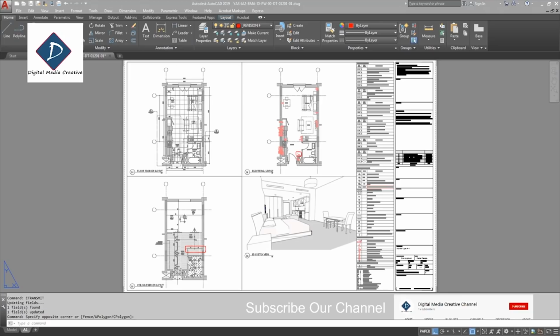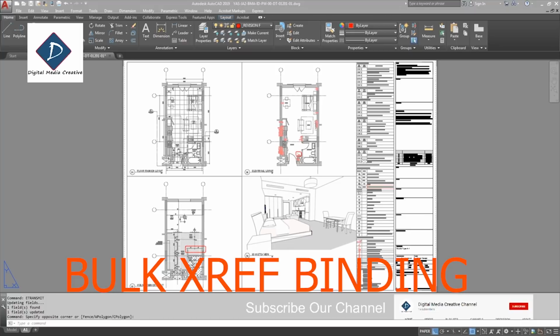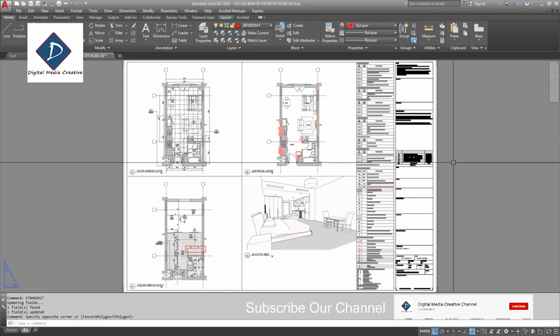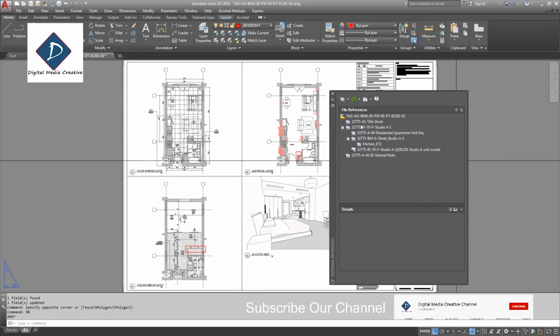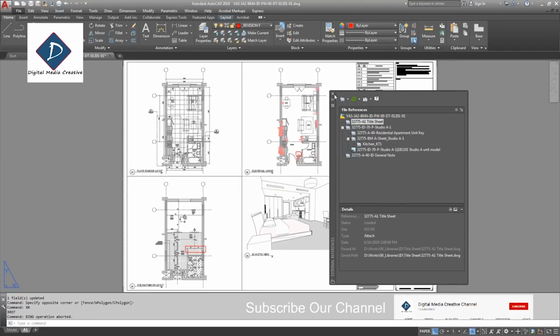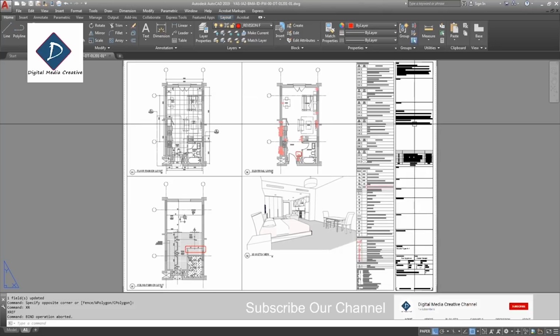Hi guys, welcome back. So I'm going to show you how to make bulk binding of xref. Normally what we'll do is open one drawing and play with xref and click bind. If you have 1 or 2 or even 10, that's fine, you can open one by one.